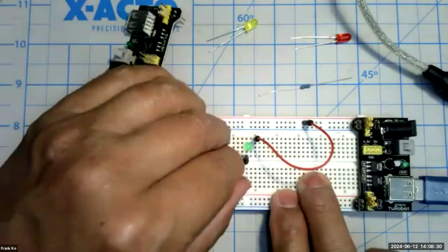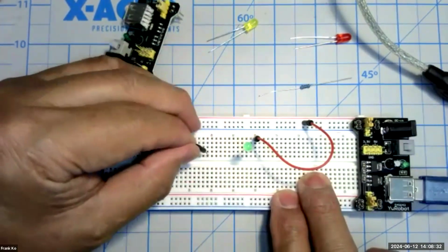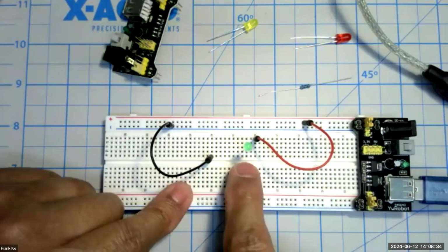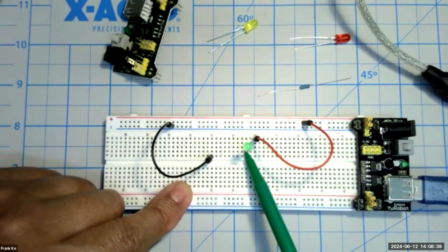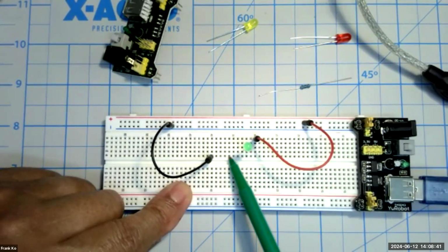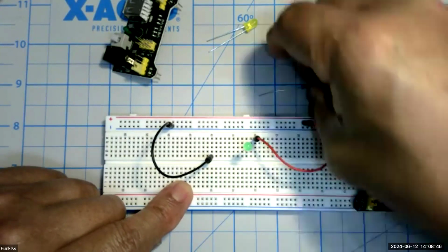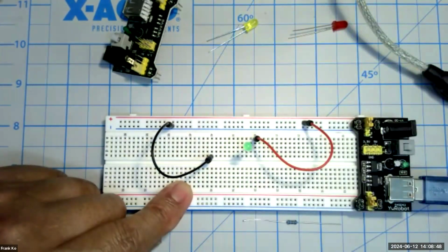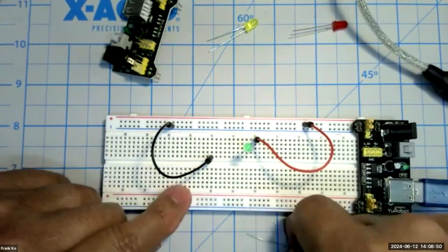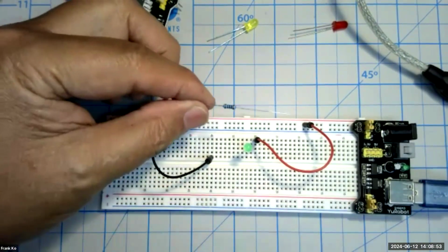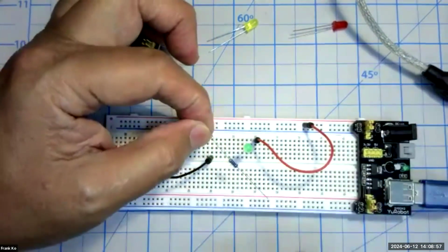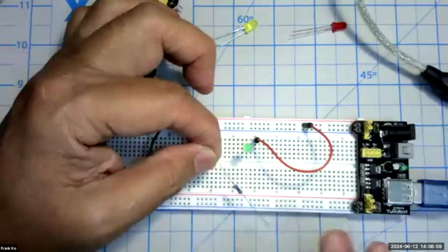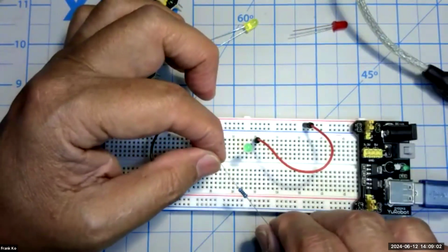So what we're going to do is take this guy, pull it over to 40E, and that will leave a gap. The gap shows we have no continuity between the short pin of the LED to the black jumper wire. We're going to fill in this gap with our resistor. So here's your resistor. The resistor has very fine leads. This is a precision resistor as identified by 5 color bands. I'll differentiate precision versus non-precision resistors in a separate topic video.